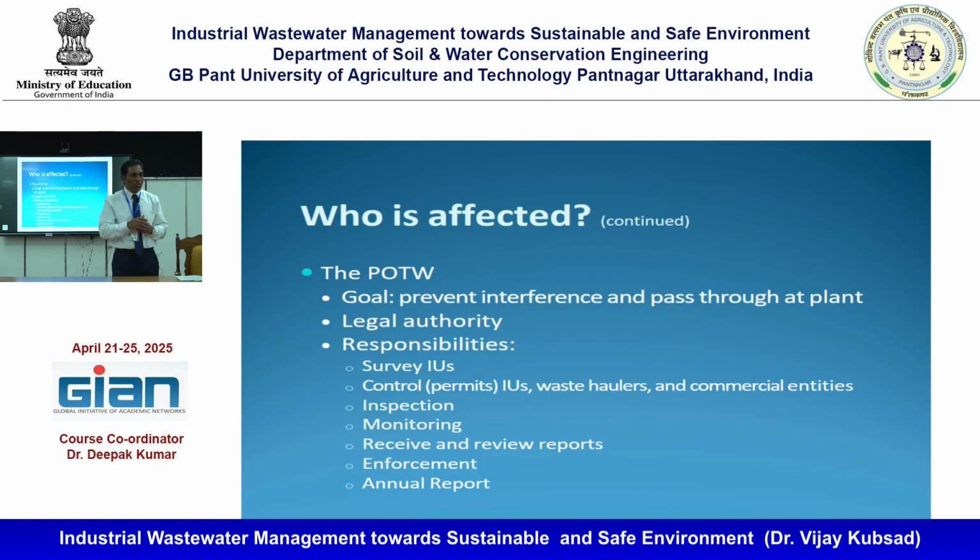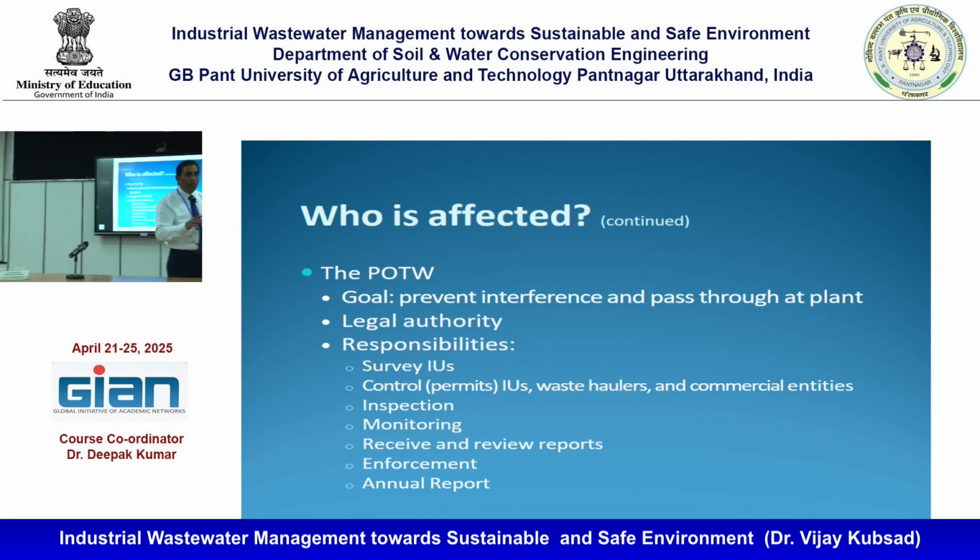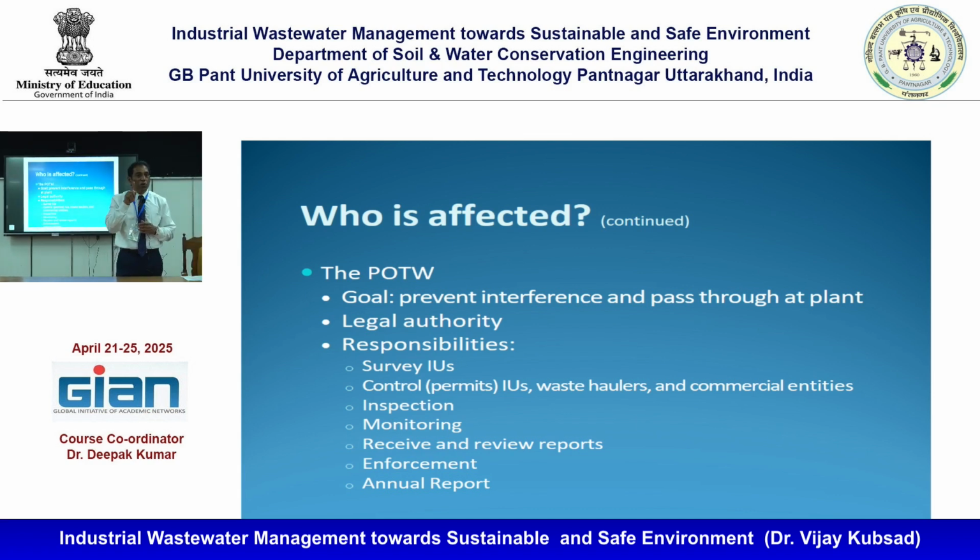Weekly you have to measure BOD, TSS, pH daily, and some other parameters, nitrate, nitrogen, ammonia, if you want to measure. Once in a week, you take a sample, send it to an authorized laboratory, tabulate all that. Monthly, you will have to report to the system, either to the city if it is delegated, or to the department.